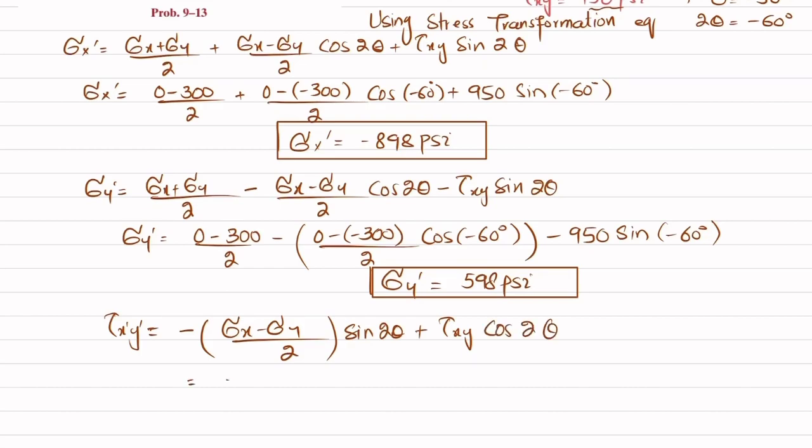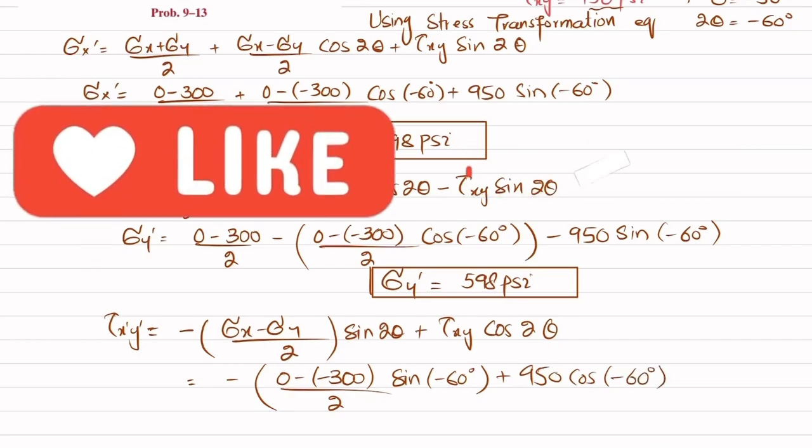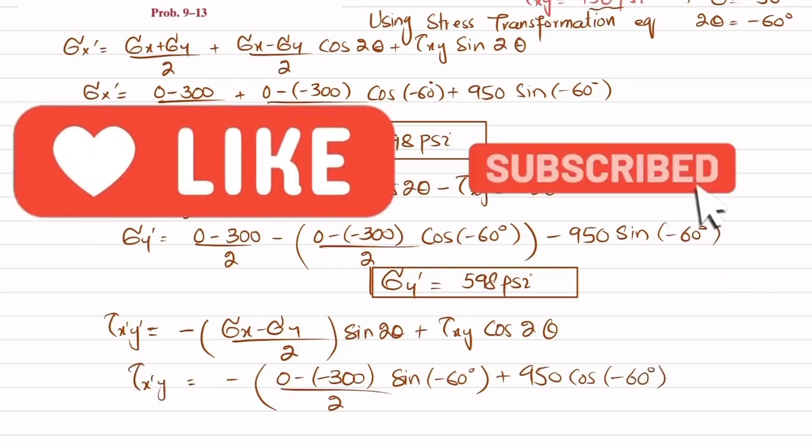So put the values: minus 0 minus, sigma y is minus 300, so minus 300 divided by 2 into sine of minus 60 degrees plus tau of xy, which is 950, into cos of minus 60 degrees.